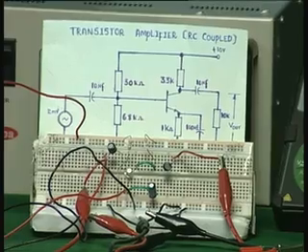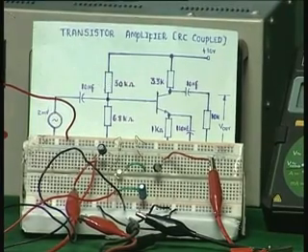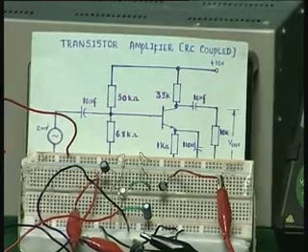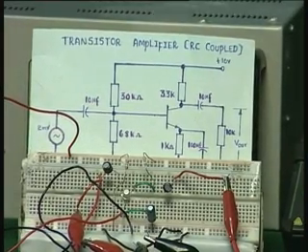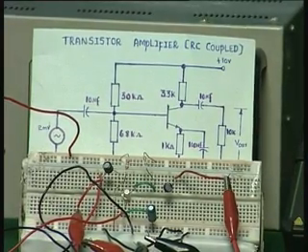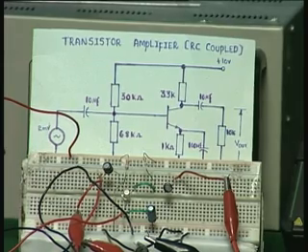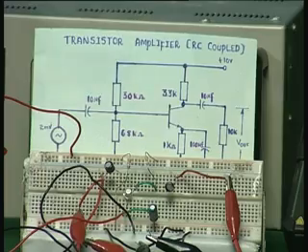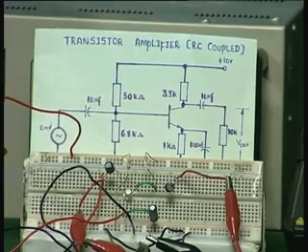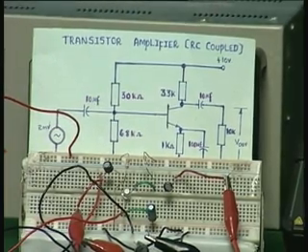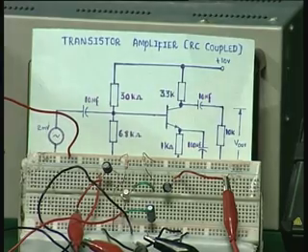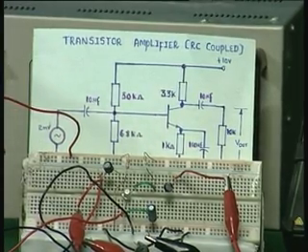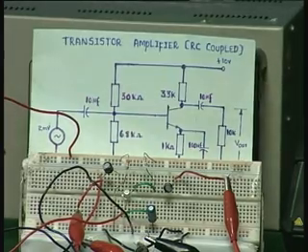Now if you want larger amplification, you can go for one more of this and couple this to the base of the next amplifier, and still you can have further amplification. So one can cascade different amplifiers and get very large gains by having multi-stage amplifiers. So we will see some of the basic theory and the model behind the transistors, and then the construction of multi-stage amplifiers, etc., in the next lecture.